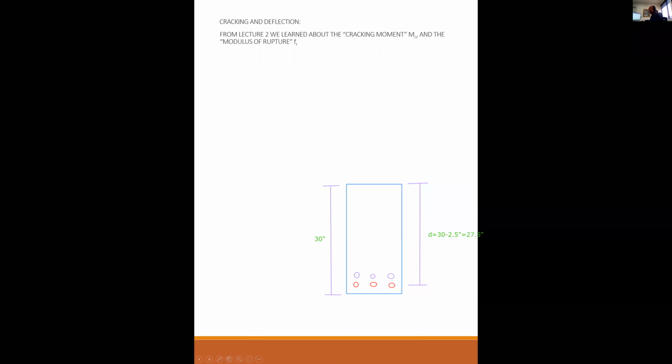Yeah, okay, so anyway, as soon as you realized that you needed 2 rows instead of 1, then you need to recognize that every time you use this 2.5 inches, that's not valid anymore. Because now the centroid of your 2 rows is 2.5 plus half a bar plus half an inch.